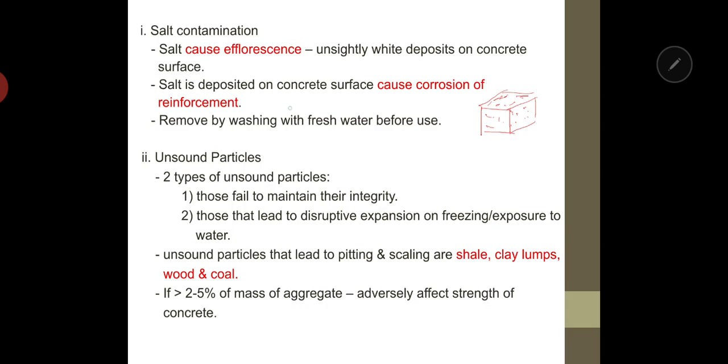Salt deposited on the concrete surface causes corrosion of reinforcement. Okay, inside the reinforced concrete, we do have steel, and if salt exists in that concrete mix, that steel will corrode. And how to remove it is by washing with fresh water before use.